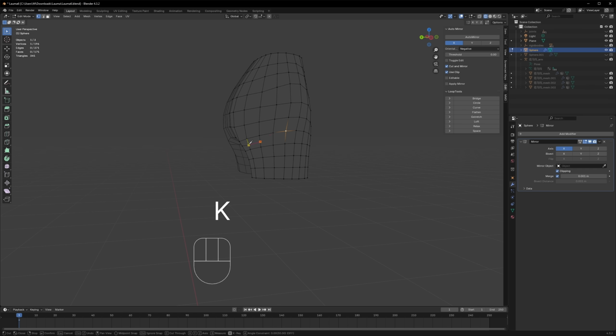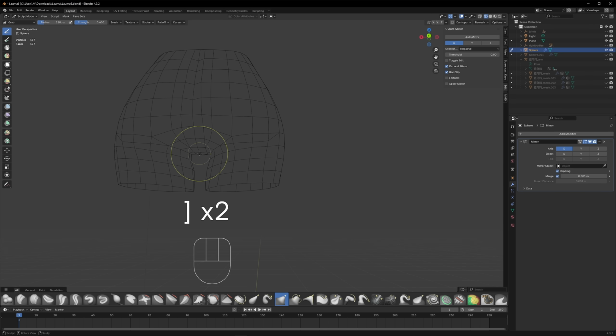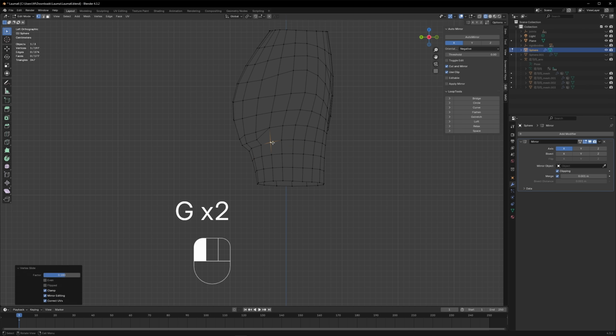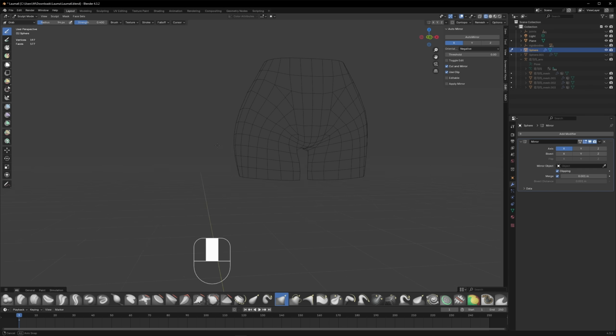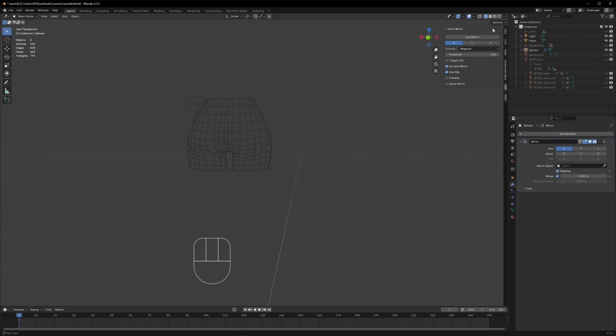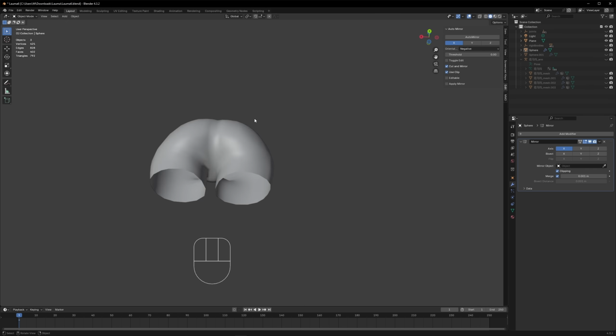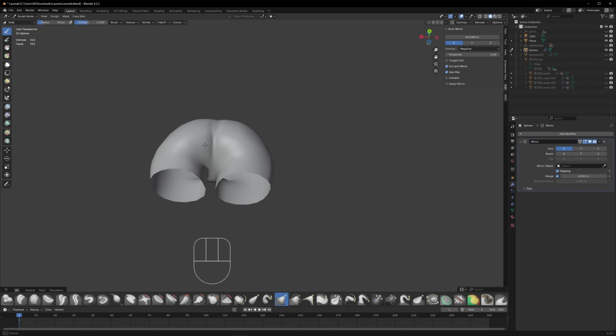I'll move those vertices under manually in edit mode, and then use the grab tool in sculpt mode to pull out the vertices that are above it. Then I'll just go over these edge loops with Loop Tools Relax, because some of them were not looking too smooth. Then I'm gonna move that loop that I created earlier inward to create that final detail.